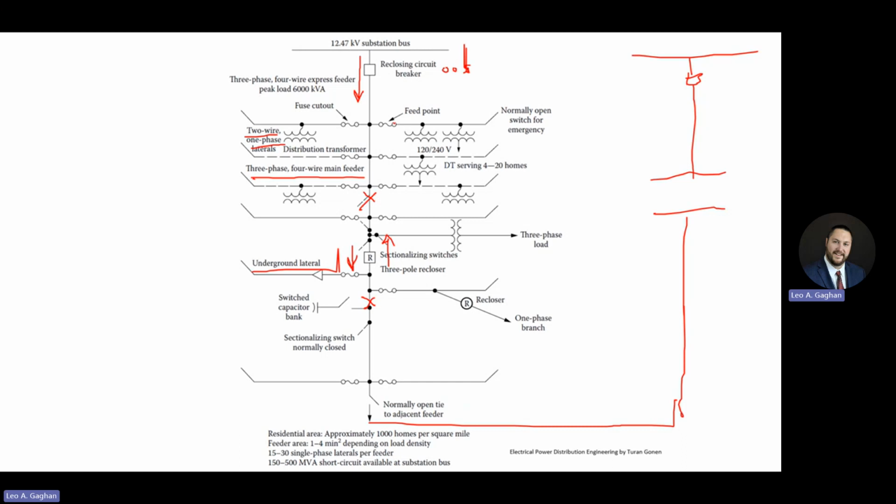And you can even almost take that a step further and say, okay, maybe the fuse didn't blow, but the breaker tripped, and we damaged that fuse to the point that it no longer has that same characteristic. It has a more sensitive characteristic because it's been damaged and weakened. And then the breaker recloses, the fault's still there, and maybe then the fuse does interrupt it first. And again, maybe acceptable with the utility you're working with, it may not, but it's a consideration.